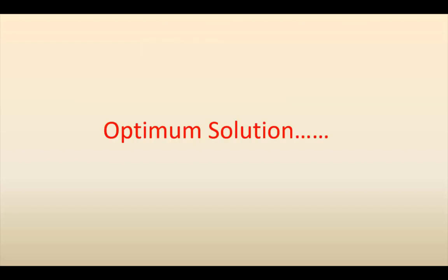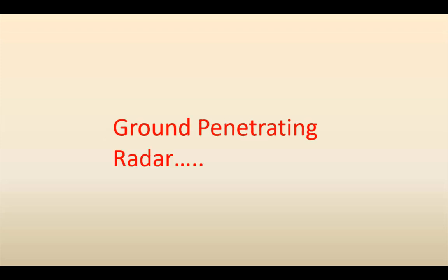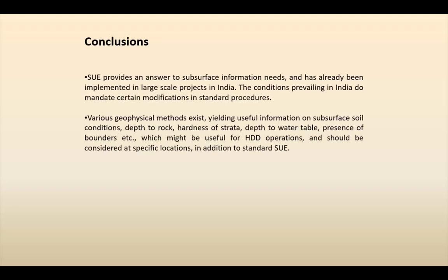The optimum solution in terms of geophysical tools worldwide, based on so many projects and experiences, has been ground penetrating radar, one of the critical components for quality level B data gathering, and induction locators. These two are indispensable tools. Other than that, of course, you have acoustic tools. You can use magnetic locators for manhole detection in case they have been buried by road layers, but these two are the minimum tools to be used in each SUE project when it comes to designating the utilities.